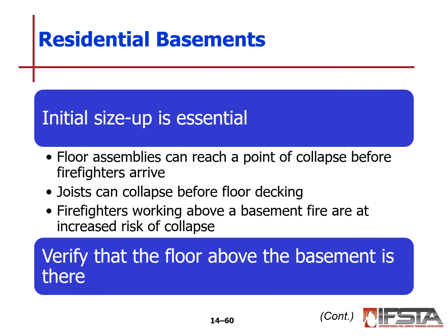With residential basements, the initial size up is essential. Floor assemblies can reach a point of collapse before firefighters arrive. Joists can collapse before the floor decking. Firefighters working above a basement fire are at increased risk of collapse. We should verify that the floor above the basement is there.